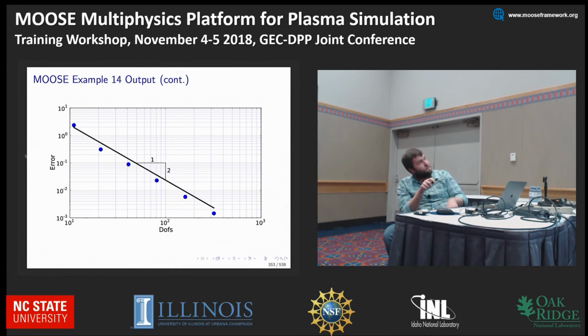If we have something that drifts off this way or drifts up this way, then we know that we're not quite right as we get an increasingly refined mesh. Then we can say, okay, we're looking good on a coarse mesh, but not on a fine mesh. Why is that? Let's see if we can address it. So this gives you like a thermometer, a check.